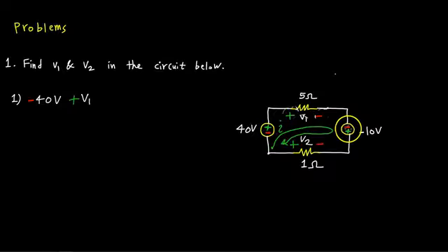Then I'm going to see here a minus sign, but the voltage itself is negative 10. So let's just call this guy Vx. And then I'm going to say plus V1 minus Vx. As I just mentioned, I'm going to manipulate that variable, not the value, initially at least. So I'm going to see the minus, so I'm going to write a minus Vx, regardless of what that Vx is, and we're going to save that here. We're going to say Vx is equal to minus 10 volts, just to keep that there.